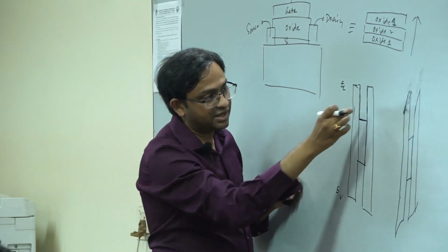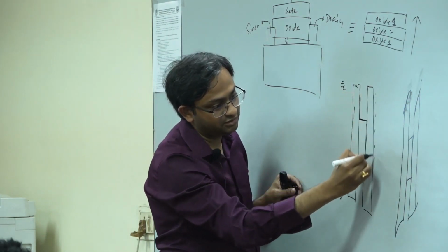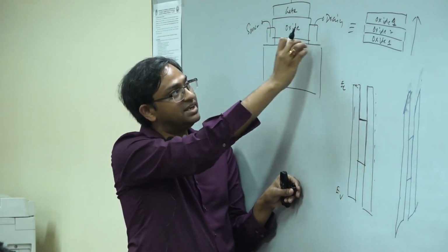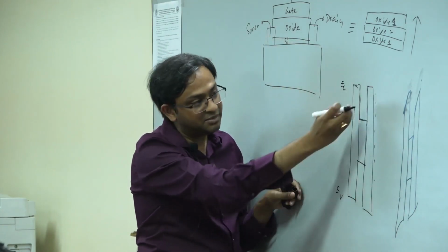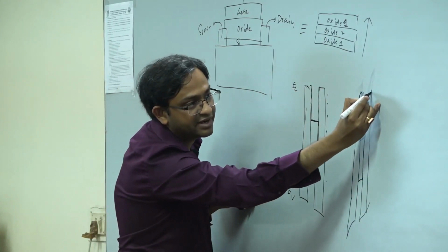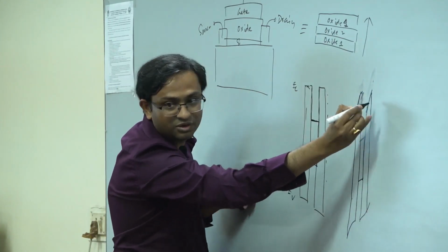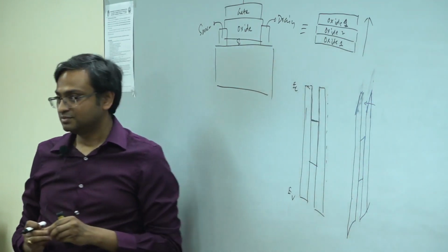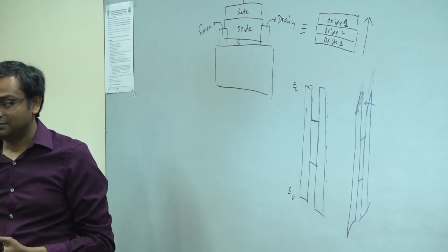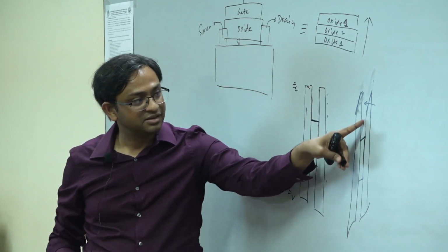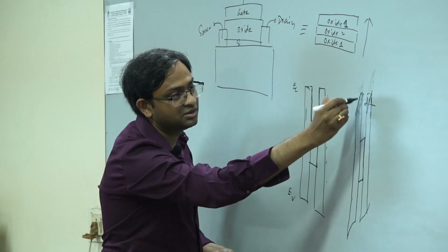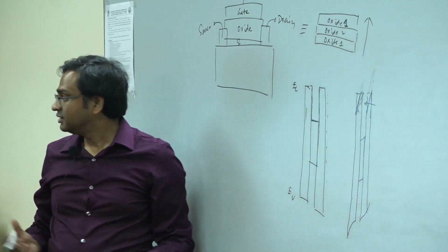Now you see that there is a channel over here, remember, which has a lot of electrons, because we have now inverted it. So the channel is here. There are a lot of electrons available, but they cannot go in because there is a barrier. But now when I apply a bias, you see the barrier has become thinner over here. Make sense? Through which they can now quantum mechanically tunnel. Make sense? And once they are here, they are kind of trapped. Now if you remove the bias, then the charge cannot go back and it kind of stays there.